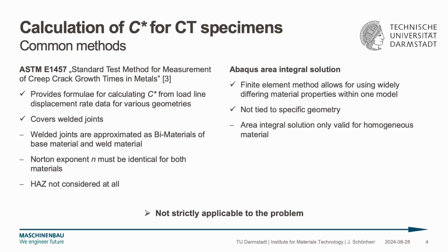And as you have seen, we have built a finite element model, so one can assume you can also calculate the C star integral. It's basically derived from the J integral, but as a rate solution, considering the strains as strain rates, and therefore you can also calculate a C star integral or a C(t) integral for times to infinity in Abaqus.